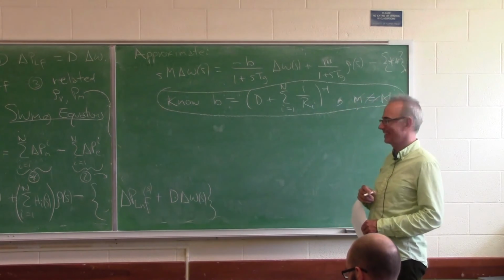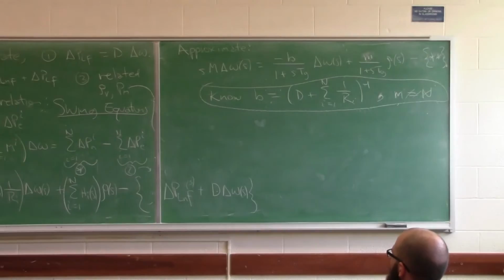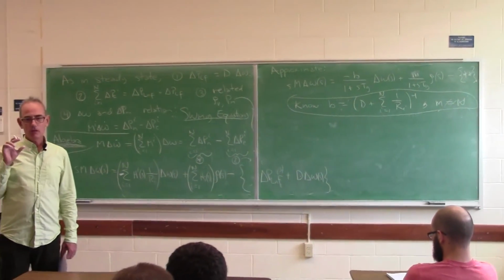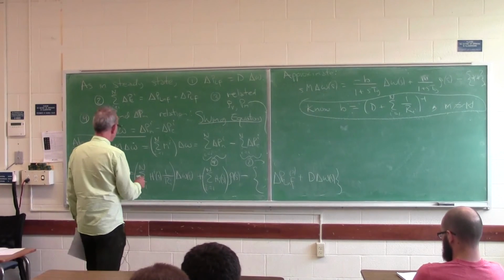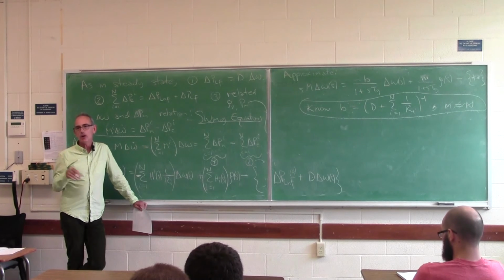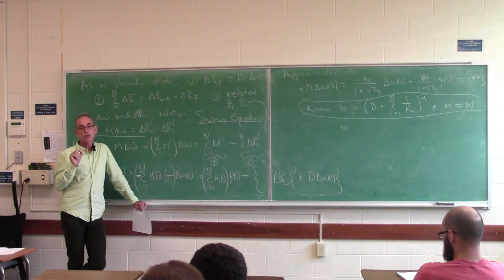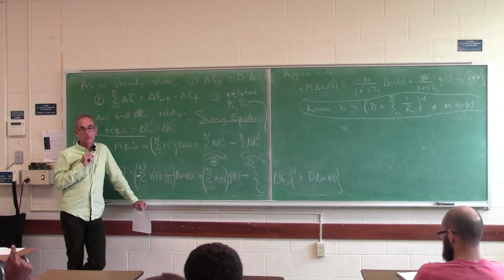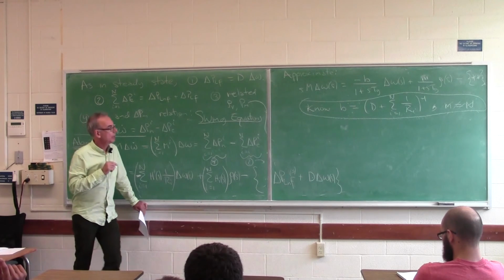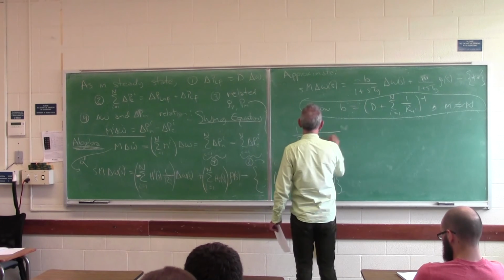Yeah. So I'm not getting it: on what basis is H_i the same? Because we designed them, okay? So we set droop gains, and remember these came from two components. There were valve dynamics, which we'll assume are fast. If they're not fast, you have a crappy generator, you should upgrade. And the rest of it's the governor dynamics, which are designed very carefully by all sorts of rules. There's an integral gain, which is going to be set by standards. So when we derived the governor dynamics, we got the equation 1 over 1 plus sT_i, right? The main thing that we saw was this.